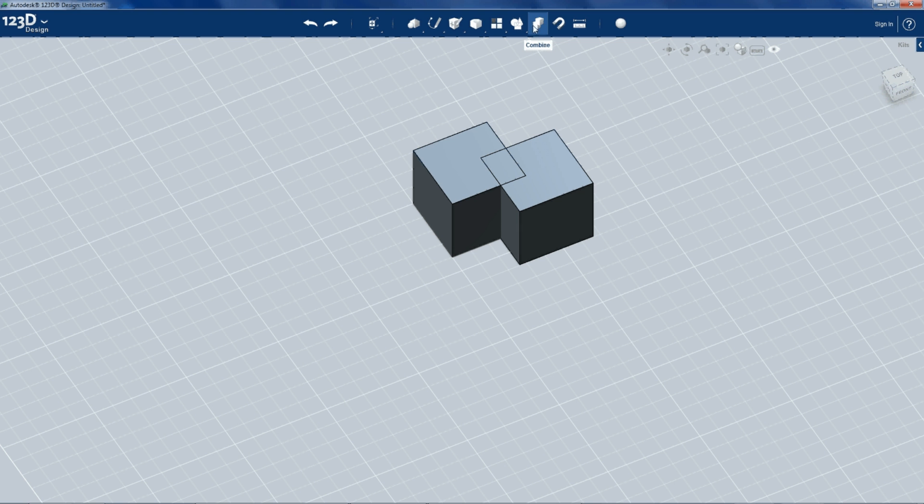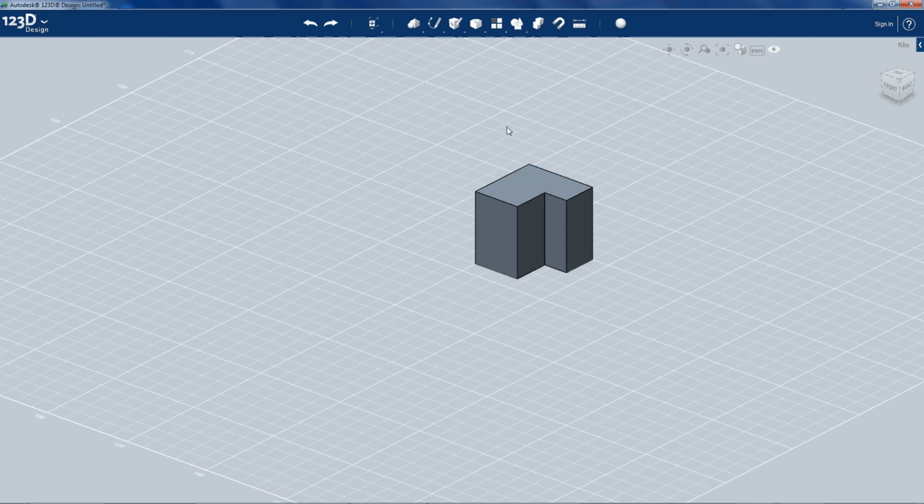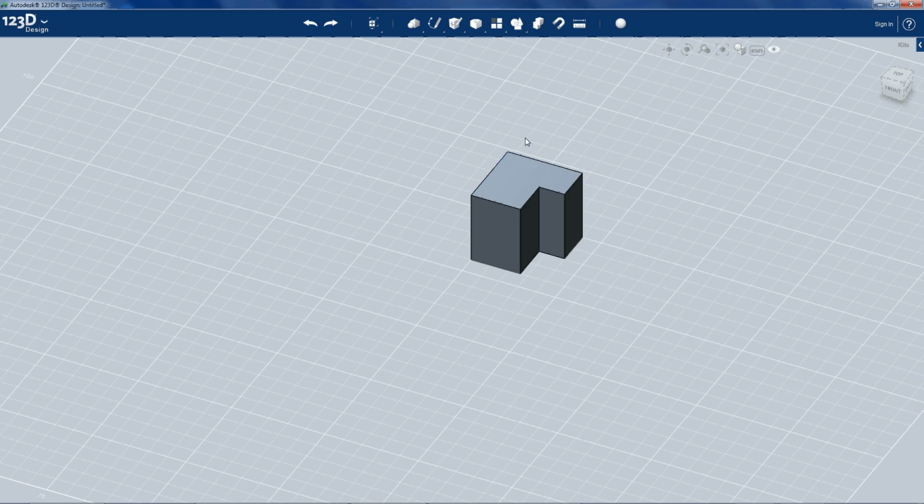And now I'm going to go over to the Combine tool in the upper menu. The Combine, this is kind of a Boolean operation, which you can invert. So I'm going to pick the tool, pick my first object, and then go to this little settings flyout, click it, and say subtract. And then click the second object, and now it's sort of thinking, and then just click into space to cancel the command. So it's done a Boolean subtraction, which is pretty good.